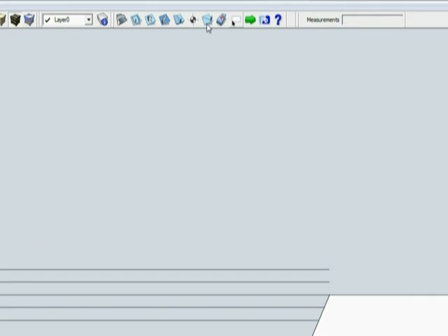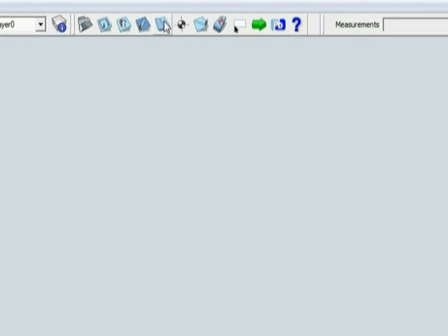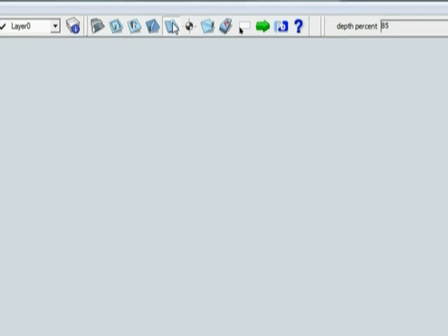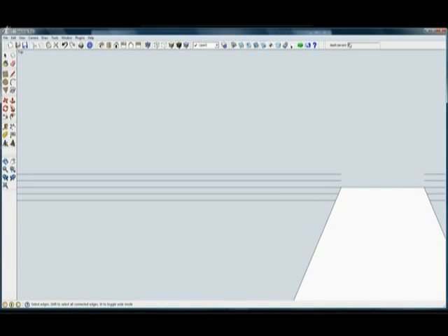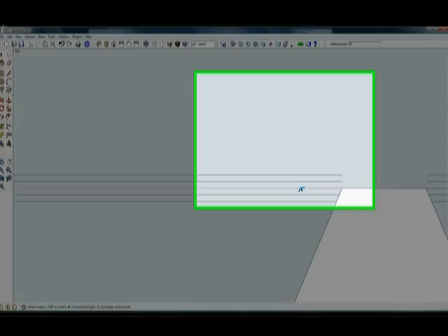But maybe I want to set my fold tool, and I'm just going to use the default values. Again, I've showed you how you can experiment and use different depths of cut. But perhaps we want to do, I'm going to toggle over to 75%. And if we highlight this middle line and we click on that, now we've got a 75% cut right on the hinge line.